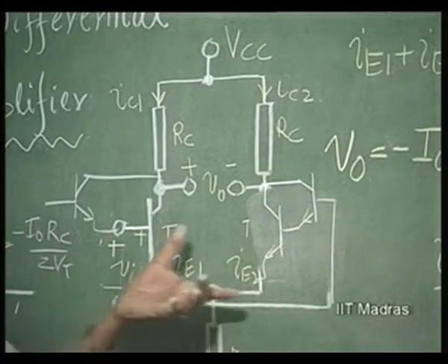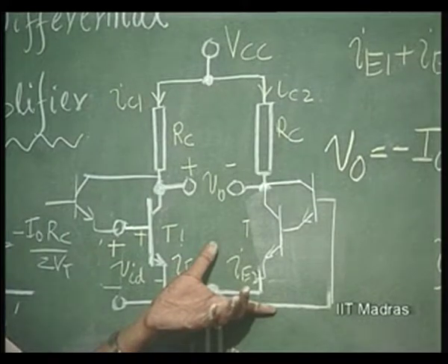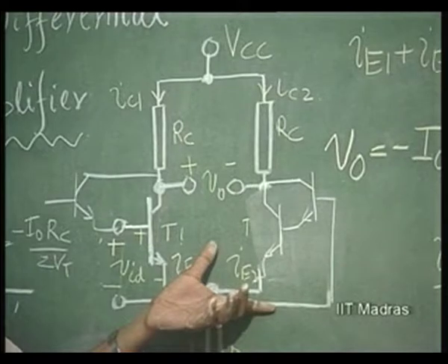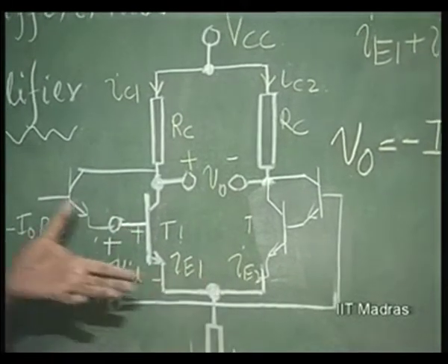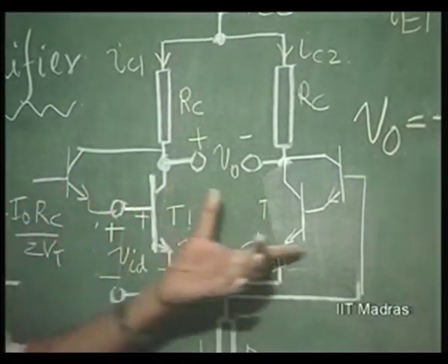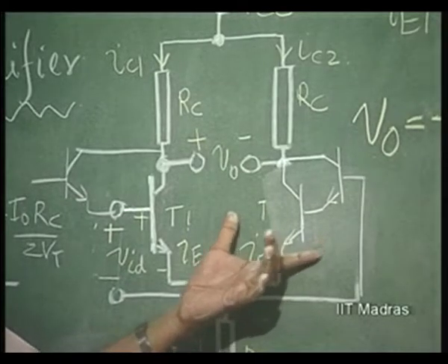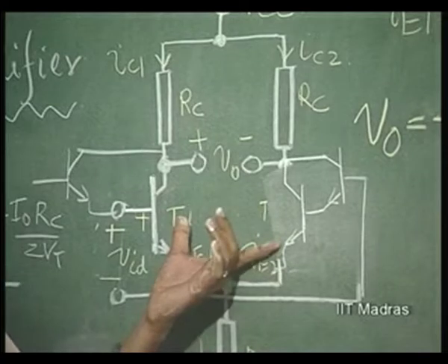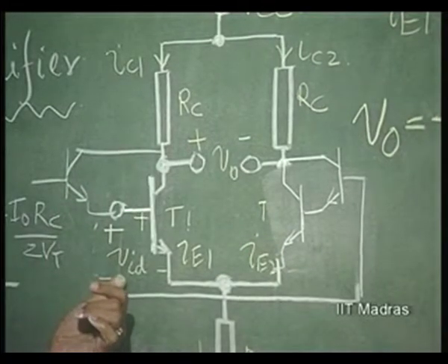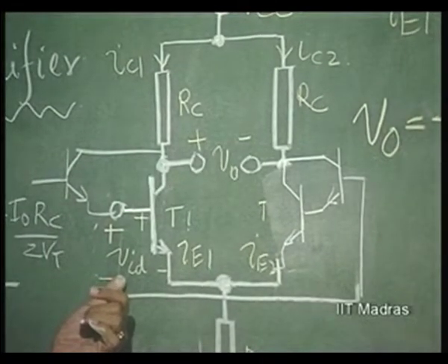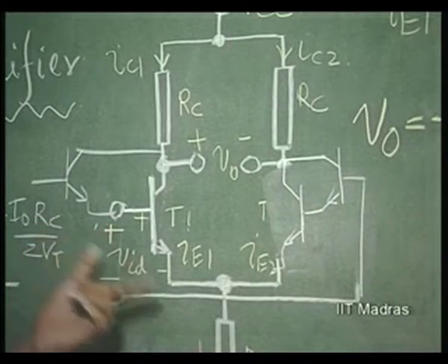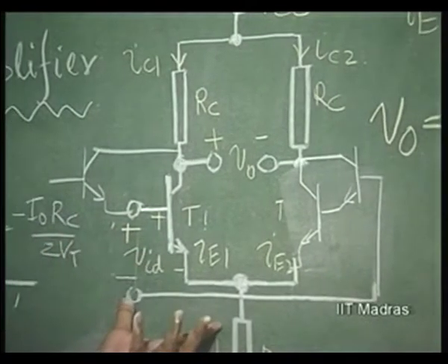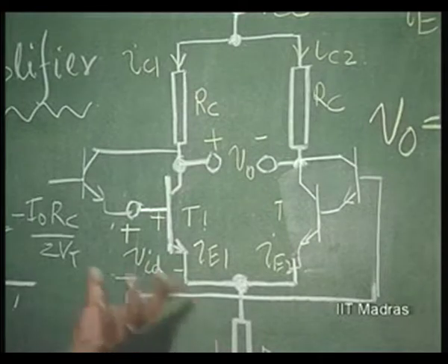Now, there are two pairs coming into the picture, so the uncertainty will be double, right? So, it will be 2 to 4 millivolts. Using more pairs of transistors will result in more input offset. Even though you might put this in order to improve the beta of the transistor, you will degrade the differential amplifier in terms of its input offset.